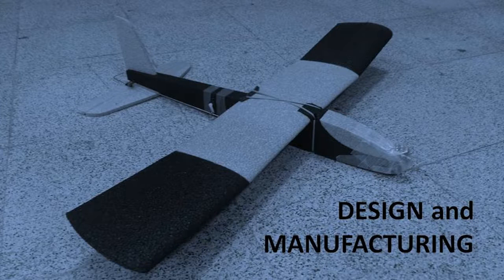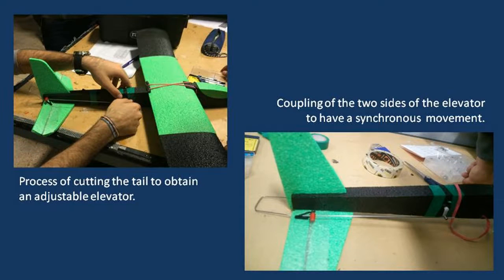Design and manufacturing process. First of all, in order to make the adjustable elevator, we cut the tail into two parts. After that, we realized that we did not have enough material to connect both sides of the elevator to the servo motor. Consequently, we had to couple both elevators to synchronize their movement by using a U-shaped rod. During this experiment, this practical solution showed good performance of the glider, and there was no significant effect on the position of the center of gravity.